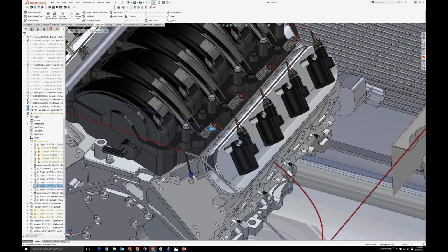That's useful for creating a flattened document, and you can use that to route off of your existing geometry, but there's no wire information. So there's no way that I can tell what's inside there unless I manually specify later, hey, add wires to this route. So it's a process that works really well if we were doing something simple, like I've got a 6-pin connector on one side and it goes to a 4-pin and a 2-pin.